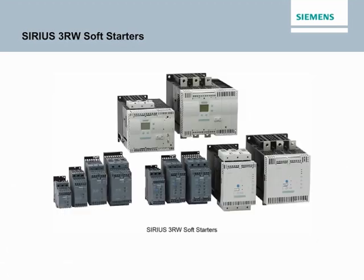Solid-state reduced voltage starters, often called soft starters, limit motor starting current and torque by ramping up the voltage applied to the motor during the selectable starting time. Soft starters accomplish this by gradually increasing the portion of the power supply cycle applied to the motor windings, a process sometimes referred to as phase control. Once the startup has completed, Siemens series soft starters use integrated bypass contacts to bypass power switching devices, thyristors. This improves efficiency, minimizes heat, and reduces stress on these switching devices.